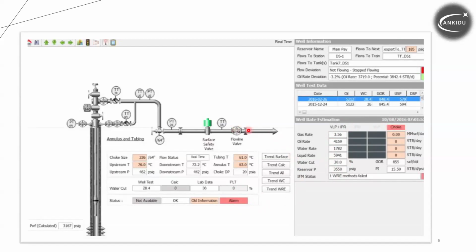We have some problem in terms of a back pressure on the flow line. There is a back pressure here. The differential pressure between the downstream and upstream is not quite enough to make the well flow. Is the choke performance not as we would like it to be? So what is the water cut? Has it risen or not? So there are a lot of questions we can ask ourselves if the well is not flowing perfectly or the well is going to be seized.